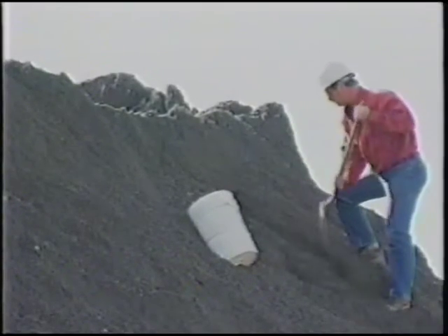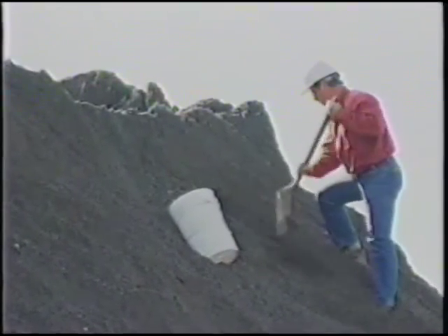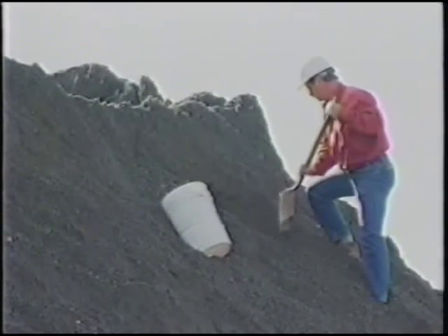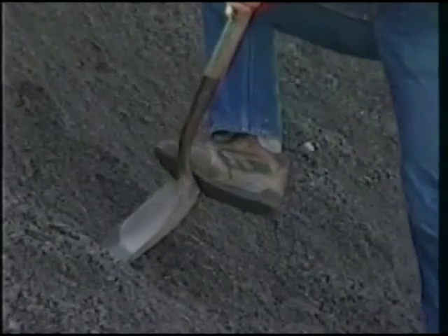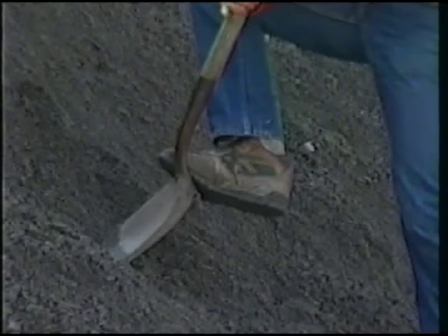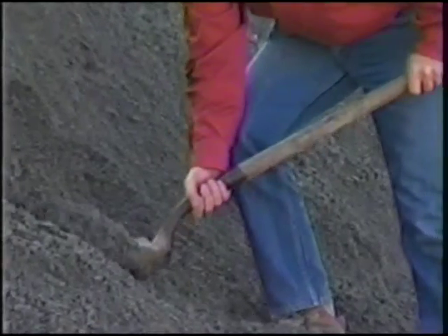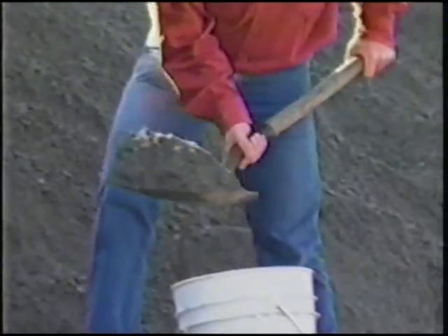The area to be sampled is opened up to expose the interior material. This may be accomplished by slicing the face of the pile with a front-end loader or a shovel. Next, the inspector uses a square-end shovel, which is inserted nearly perpendicular to the face of the exposed material, full depth of the shovel, and raised vertically to prevent segregation. At least 6 shovelfuls are required. They should be taken at equal spacing across the pile at third points of the height of the stockpile. This sampling method works best with finer materials.